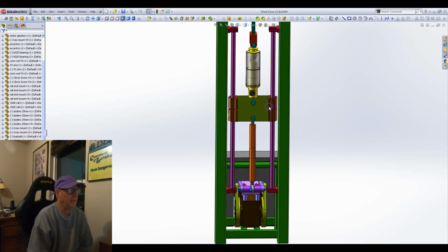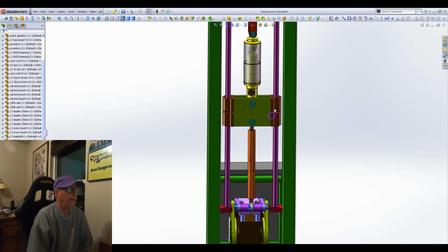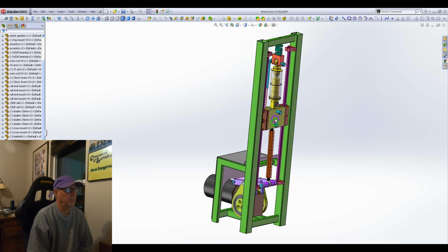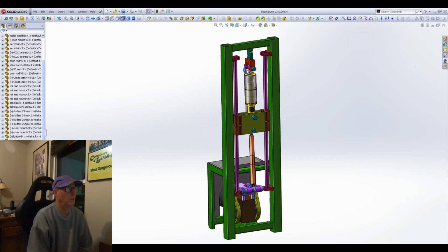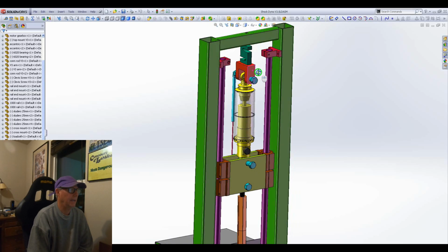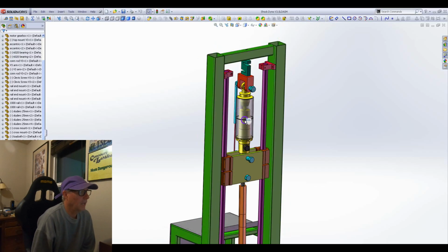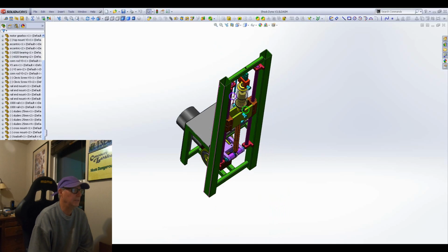So this has a linear ball bearing guide. This piece, this piece, this piece, this piece. I just added those together, so I have a little bit more L over D. And then all the side load is going into these two pairs of linear guides. That should give a nice straight actuation to the load cell. And then of course I have a heim joint on this, and the load cell can articulate all at once. So that's good. I also made it out of steel.